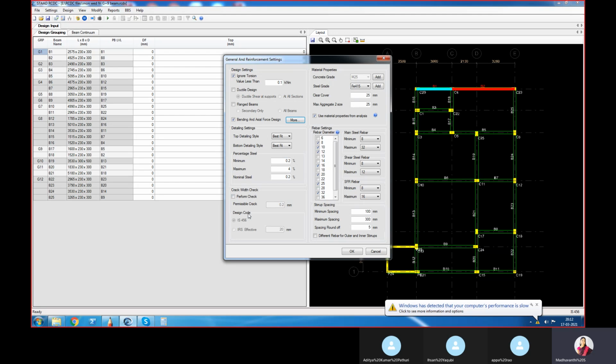But if you take a beam, it's just the member. Okay, when you compare the size of the beam and slab, it's very small. It's just the member, right? So it will not undergo much thermal crack. So it will undergo only the shrinkage crack. So that's why here it's enough to check the shrinkage crack, right? That is the most predominant, right?